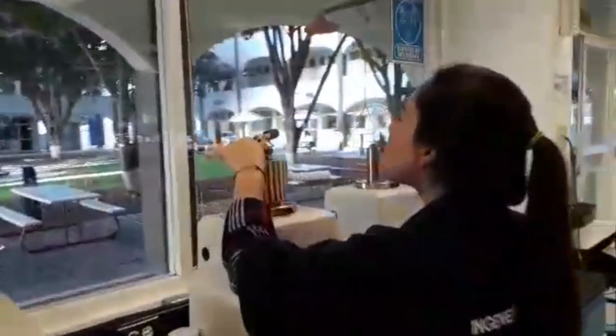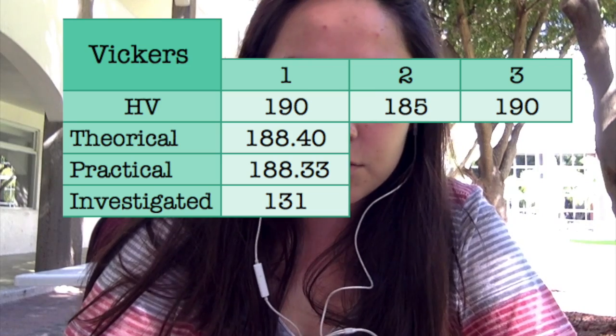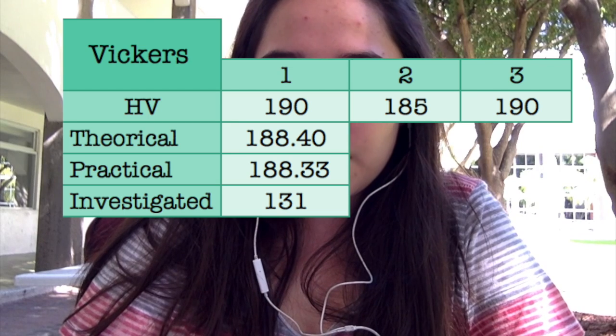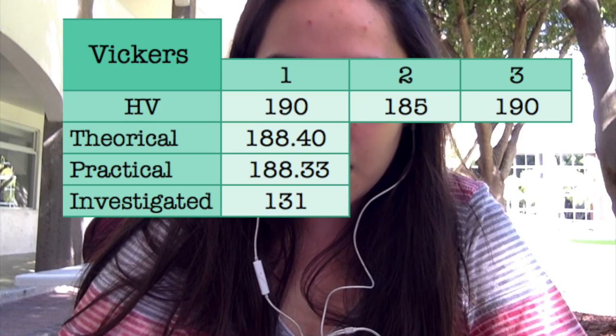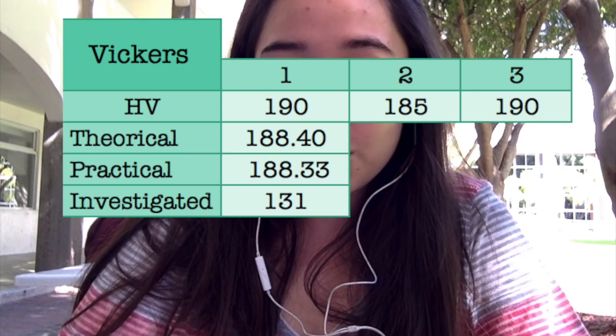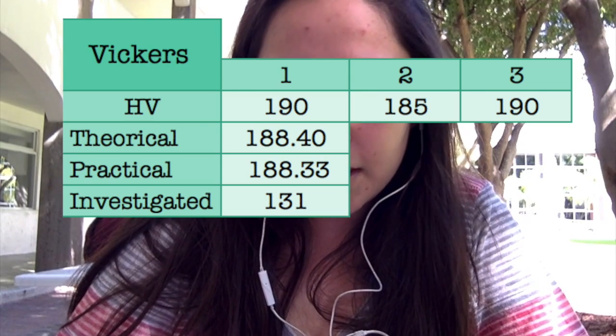For the Vickers hardness test, first we needed to make the backlight. After that we used the automatic Vickers and got the values of 190, 185 and 190. So the average of those is the practical result, which is 188.33. Then we used the diagonals of those values and the formula in order to get the theoretical value, which is 188.40. So the theoretical and practical are really similar, and the investigated one was 131, and as we can see, there is a considerable difference between the values.